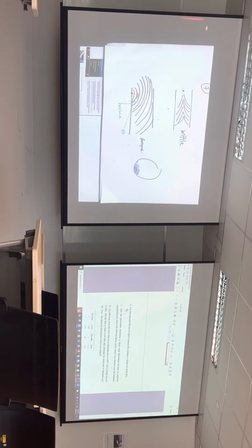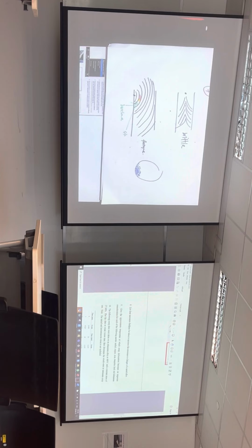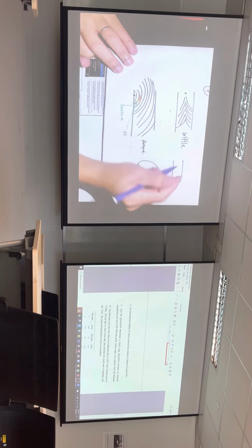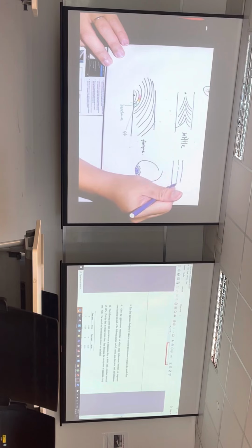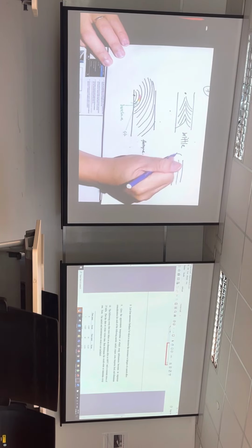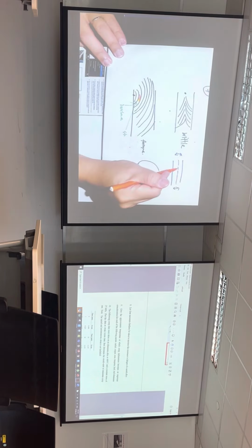And the four measures are, in very simplistic terms, that fatigue failure, for whatever reason, usually does not initiate from the center. It's always from the outside. Because if you have an object and try to do tension compression, say a beam of this thickness with this center axis, and I bend it up and down, you realize that the distance further away will have the max tension and compression.